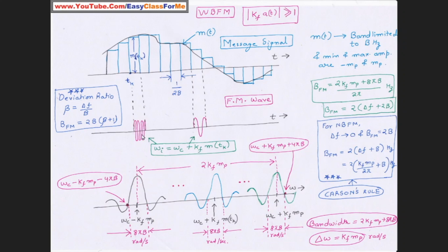So the spectrum for this particular cell will be a sinc function which is shifted to an appropriate instantaneous frequency. So might be for this particular slot the spectrum is here, and similarly for this particular slot the spectrum might be here. So we have to plot it for all possible cells, and that's how we will get these sinc pulses, and their corresponding amplitudes will vary accordingly.